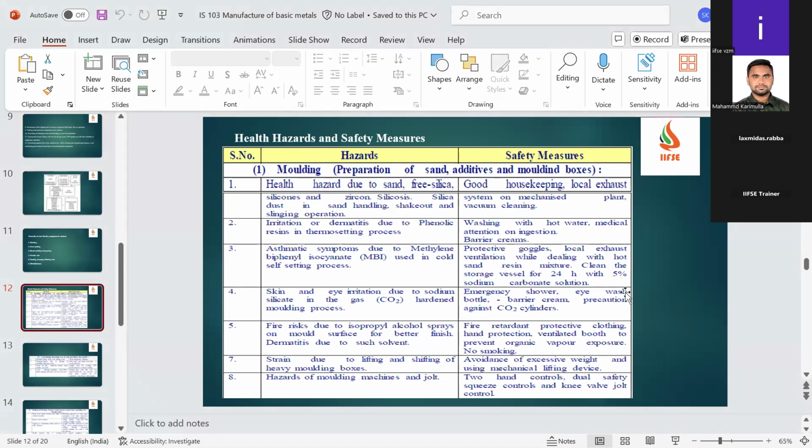That's why whenever you get contacted or contaminated with any chemical, don't think that it is less hazardous. Don't think that it is not hazardous. Don't think, okay, chalega. No, we don't know the consequences of a chemical. Maybe some chemicals will react instantly, some will react at a later point of time. So whenever you come in contact with any chemical, it is an obvious requirement that you immediately flush out and clean your body parts wherever you have contamination.